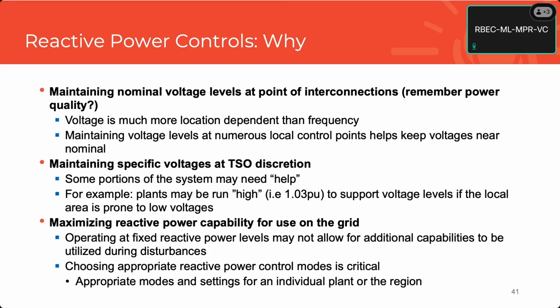Yeah, all of these normal operating controls, so active power set points, reactive power set points, which we'll talk about, all the droops, those are all things that you can test on a live system, right? So those are things you can test and verify during commissioning and compare them against your models. They're all small disturbance, small signal type things that you can test in the field without making your operators too angry with you when you're doing that.